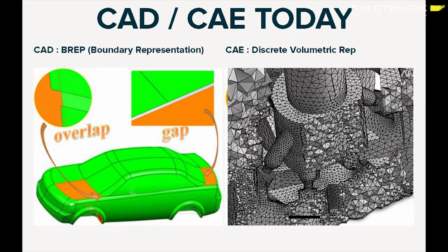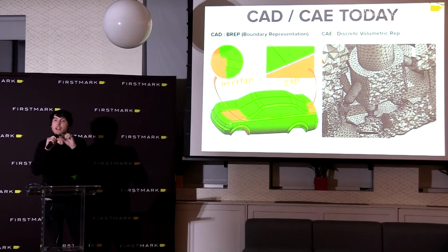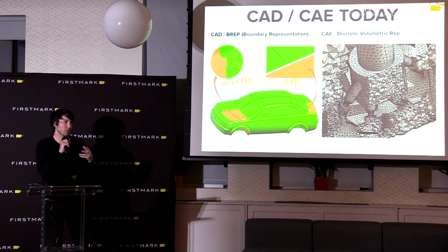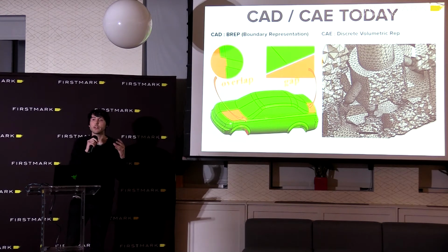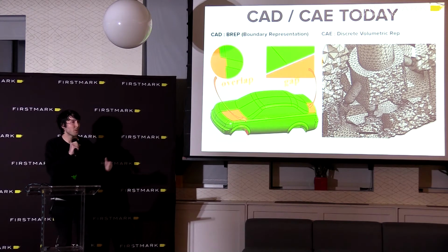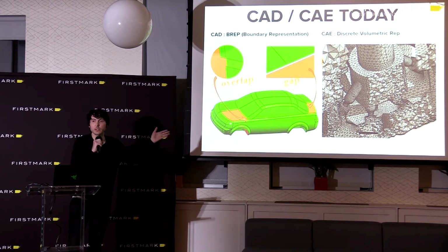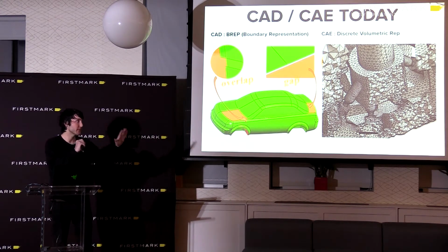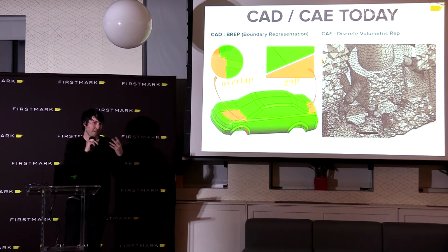And so then it helps to understand what the data structures are today that are being used. CAD is traditionally based on this boundary representation, a BREP. It's an infinitely thin surface representing a part. And so if you look at actual materials in the real world, materials have their properties because of the cellular structure within them. Wood has long, thin cells, so it's stiff in one axis and not so stiff in the other. And so traditionally, CAD never represented parts like that. They represented parts based on a boundary representation of surfaces, smooth surfaces, but patches. And so it's really kind of a fake.